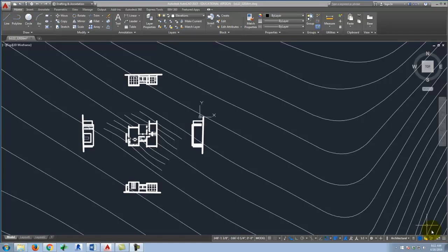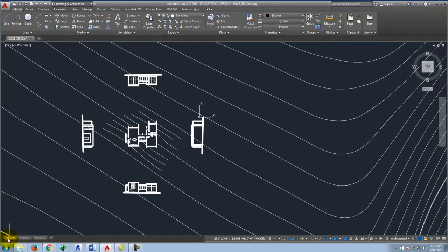What we've been modeling in thus far with the black background and the white lines is something that's called Modelspace. The idea of Modelspace is that whatever you draw is in full scale. So if a wall is 6 inches thick, you draw the 6 inches. If a wall is 20 feet long, you draw it as 20 feet. Everything is in full scale. That's denoted because we have the black background. If we look in the lower left corner here, there's a little tab, and it's behind me, so it's impossible for you to see on the screen. But there's a tab that says Model, and that is Modelspace, and that's what we're currently drawing in.